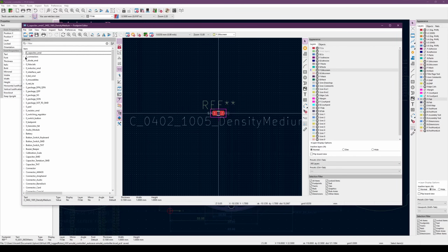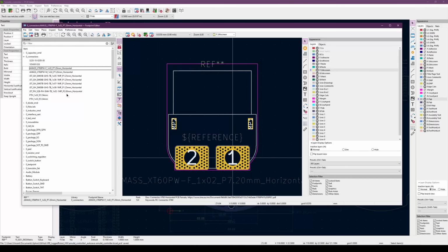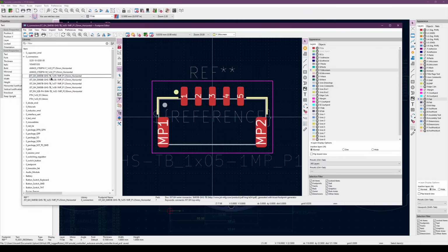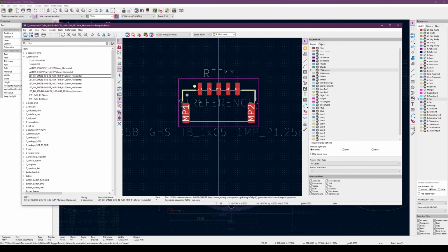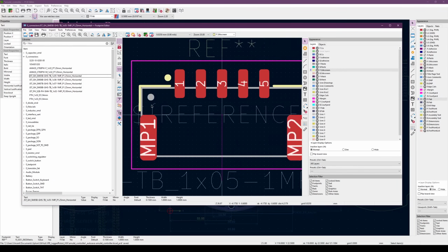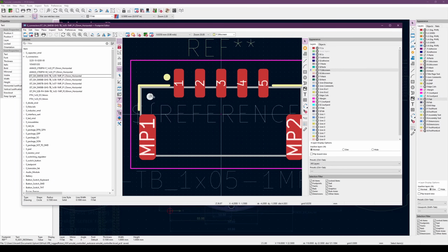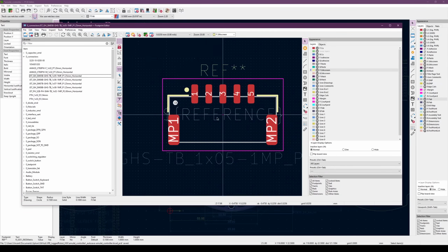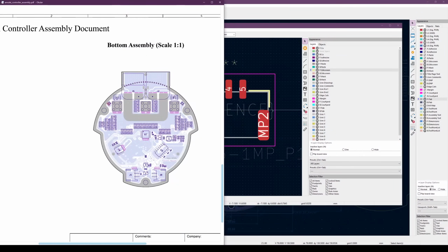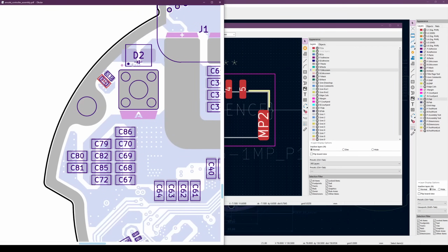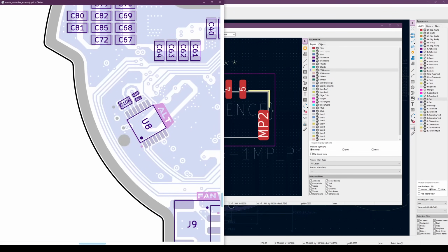And this is a very easy way to keep the schematic clean. And I recommend doing this in most of the components for the fabrication layer, because this text is often not very useful. I also like to add polarity or an indicator for the pin 1 on the fabrication layer, so that we can see on the final assembly file the polarity of each of the component.